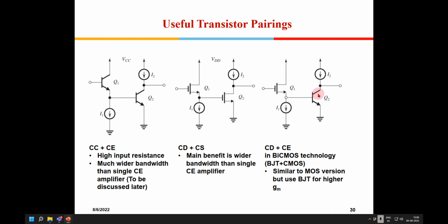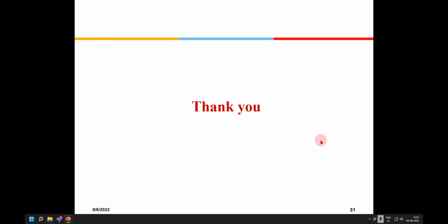In the last stage, we generally try and use a BJT, because that has got a higher current capacity. There are other configurations also, by CMOS. This is one of the BiCMOS configurations, where in the final stage you have a BJT. Before that you have MOSFETs. These things are also done in most of the VLSI chips, so you should know this.